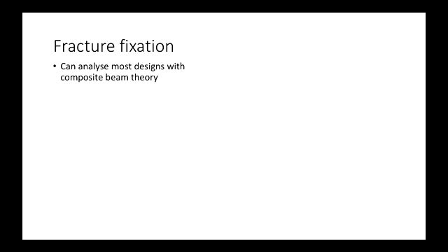So for us as engineers, how do we design these fracture fixations? A lot of the designs can be assessed with composite beam theory. Have you done any beam theory in previous years? Yeah? Some? So, an extension to that: when you normally do classical beam theory, you just have one material, but you can extend it to multiple materials.